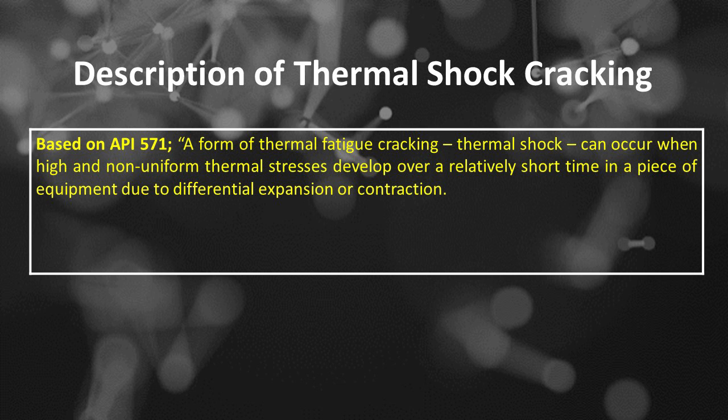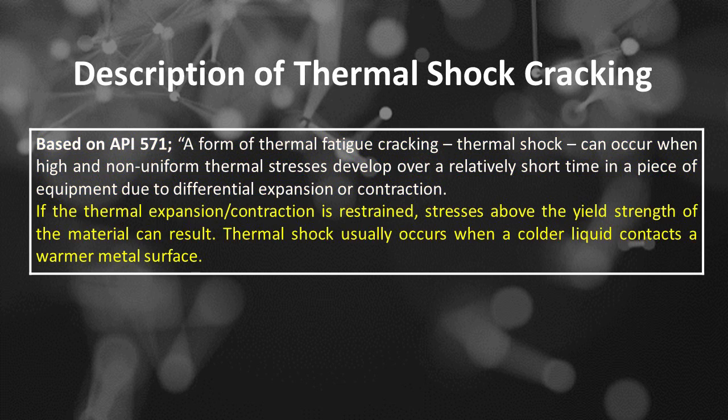A form of thermal fatigue cracking, thermal shock, can occur when high and non-uniform thermal stresses develop over a relatively short time in a piece of equipment due to differential expansion or contraction. If the thermal expansion/contraction is restrained, stresses above the yield strength of the material can result. Thermal shock usually occurs when a colder liquid contacts a warmer metal surface.